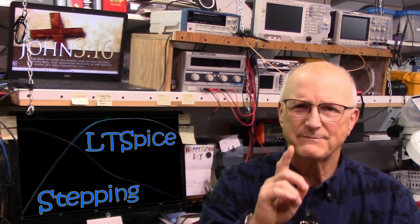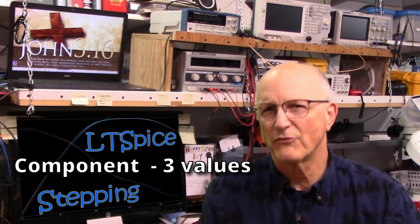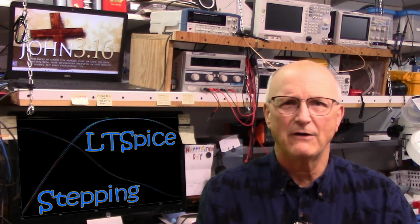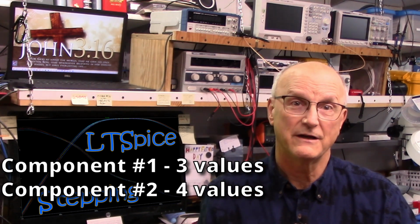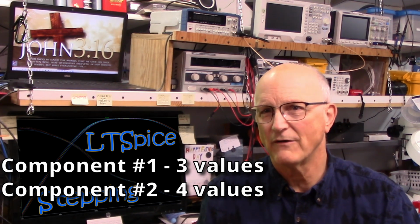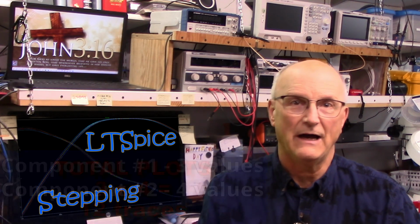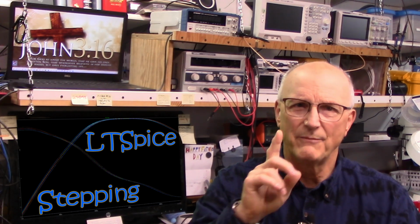Now, I have one last point for you that's very important to know. If you specify stepping through 3 values on 1 component, you'll get 3 plots, 1 for each value. Now, suppose you step through 3 values on 1 component and 4 values on another component. LTSpice will step through every value of 1 component for every value of the other component, giving you 3 times 4 or 12 traces to view.